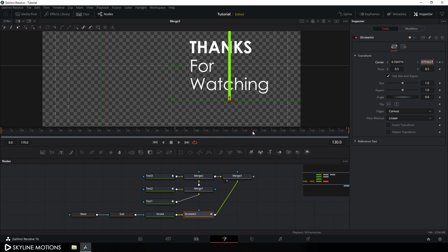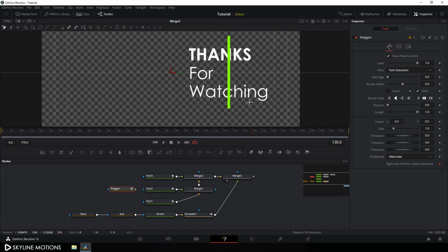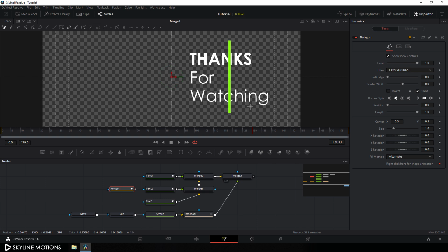And now I want to erase this text along with the line. So what we have to do, we have to take a new mask. So click on this polygon button to add a polygon mask. Drag it over here, hit F2 on the keyboard, call it polygon. Hit OK. And now I'm going to create a polygon mask.